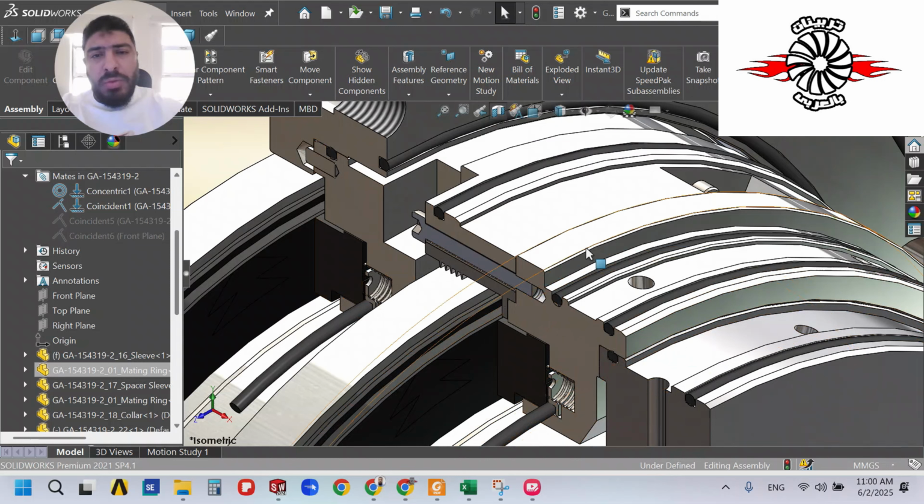And there is also nitrogen injection as a secondary seal injection, to prevent any gas coming from the atmospheric side or the primary side, and to direct all the gas vent, either seal gas or nitrogen, to exit from the primary gas vent through these openings and hose.